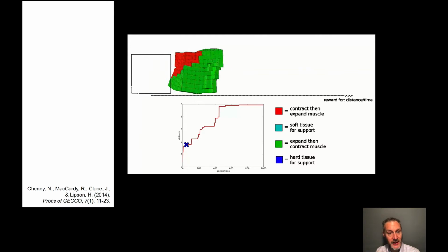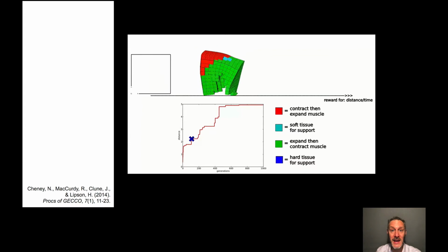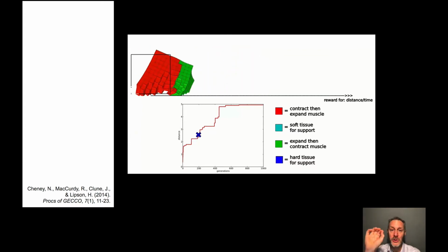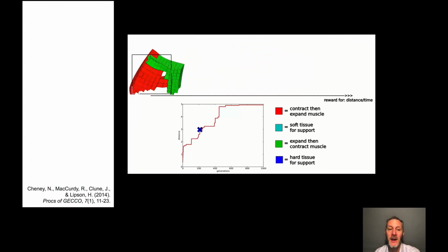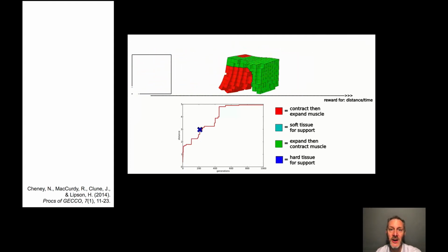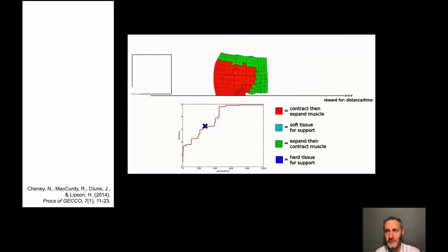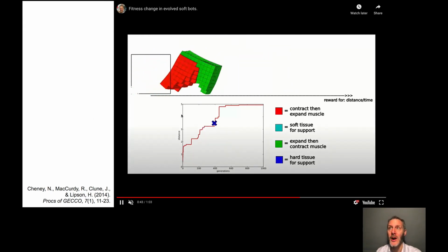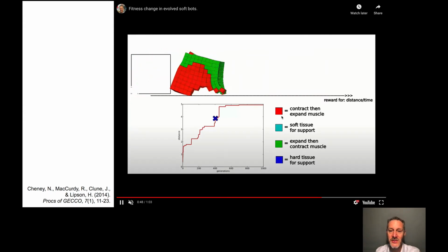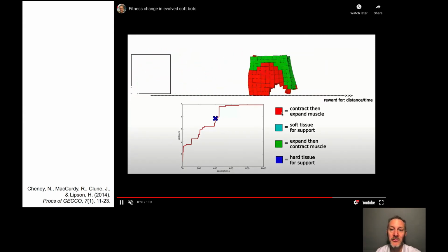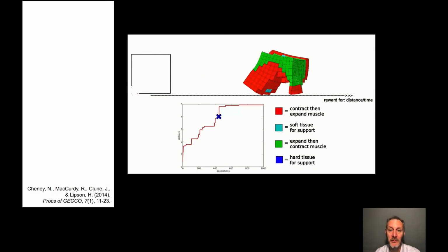So what the evolutionary algorithm does in this case is each piece of DNA in the population places voxels within this empty cube at the beginning, and then it also paints different colors onto these voxels, where the color dictated by the DNA represents material properties of this soft-bodied agent. You'll notice that many of these agents are mostly made up of red and green voxels. Red and green voxels here correspond to the soft robot equivalent of muscle.